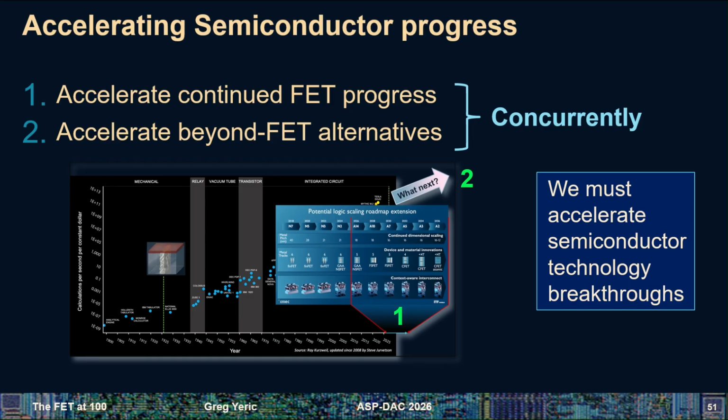Now, let's say the transistor person does that, then the circuit designer comes in and says, well, my circuit, I'm going to guard band a little bit, and then the system guy does. Because these software tools are discrete, independent tools, you often get over-margining because each one can't comprehend the margining that's been done in the previous step. So there's a lot of opportunity there to reduce the power and the delay in circuits by more accurately looking at the root causes of device variation.